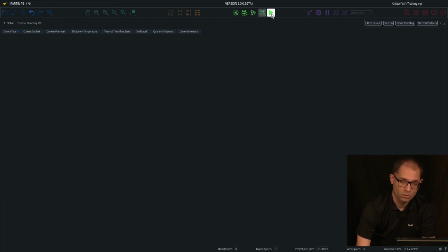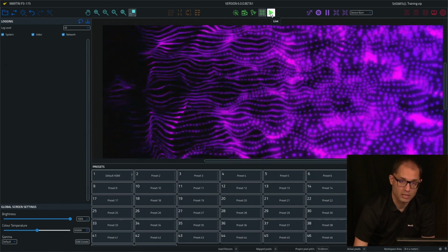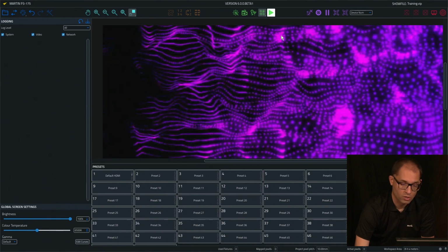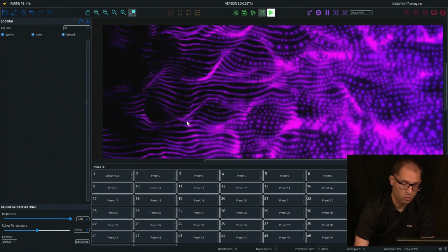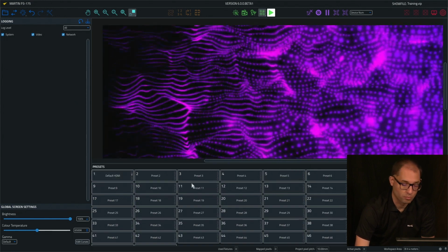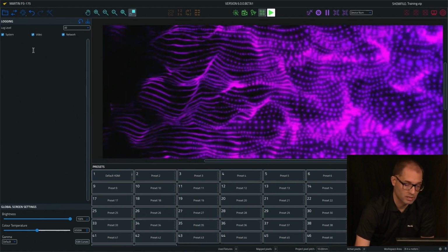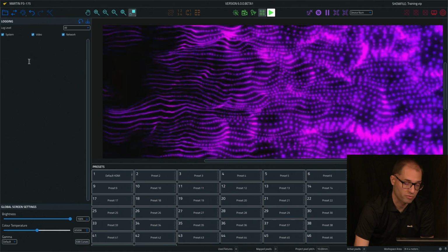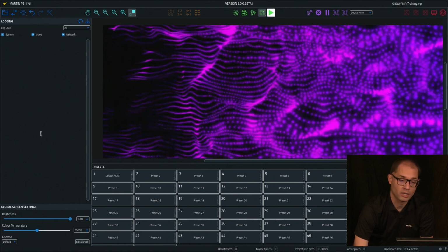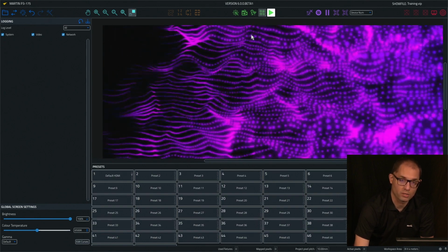The last view is the live view. This is where you typically have the P3 controller when you're done with the setup and the show is just running. So in the live view, you can monitor incoming video mapped onto the fixtures. You can trigger presets but not modify them, and you have a logging screen here where you see fixtures that drop off the network, are added to the network, fixtures that are overheating, fixtures that have errors. Warnings are all shown here in the logging view. So live view is the perfect view to be in when your show is running.